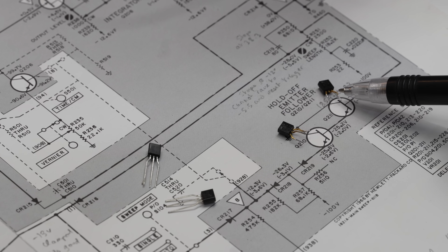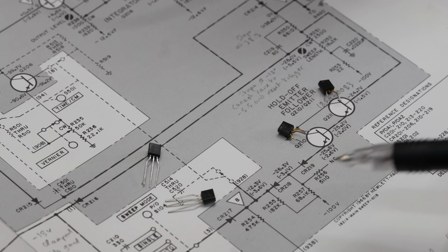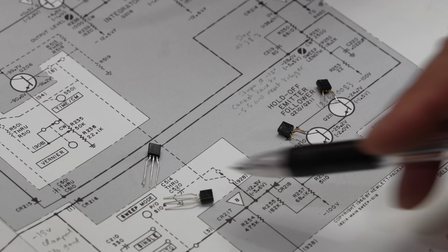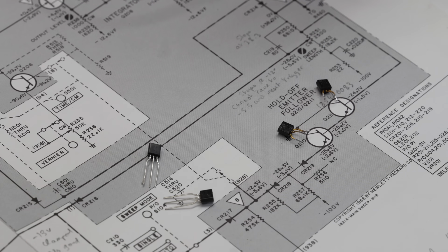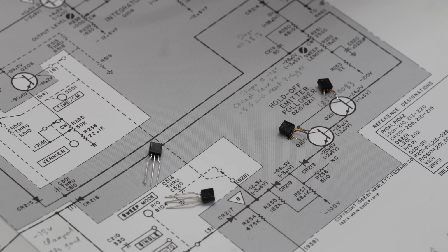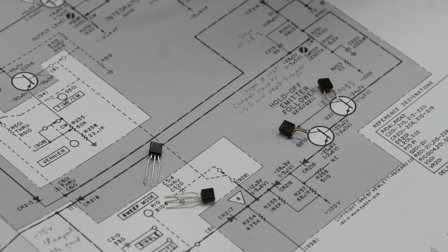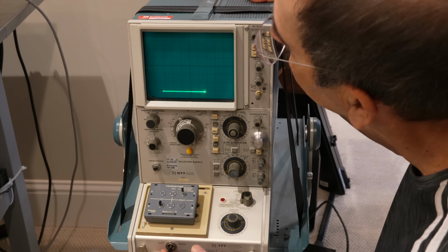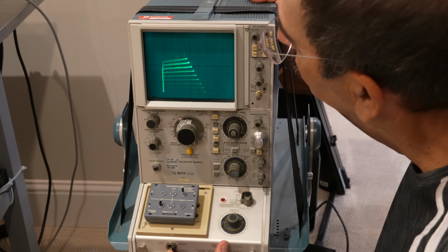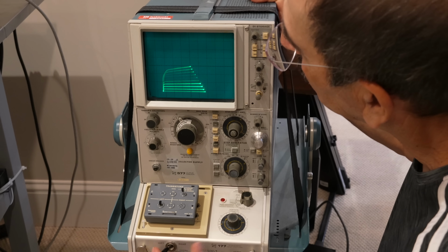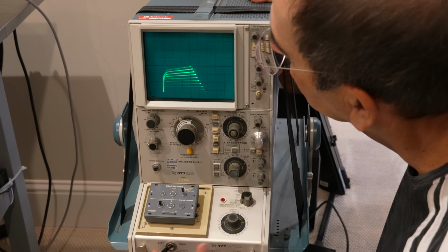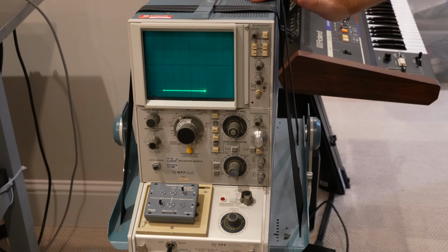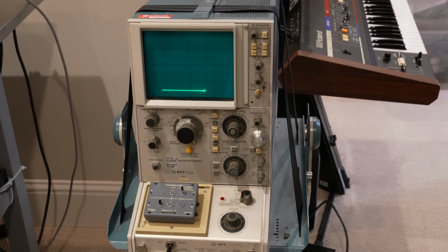This one looks like it's still a transistor on the ohm meter test. These are PN2222A. We can see what an original looks like and compare it on the curve tracer with our PN2222A, the modern version of the 2N2222A. On the left, the original HP transistor. Looks good to me. On the right, the PN2222 just has more gain, which is nothing wrong in an emitter follower. It will follow better. So that's a good replacement.